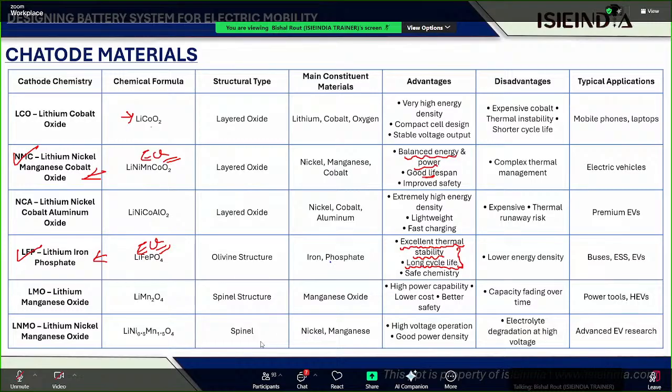So that is the reason why lithium iron phosphate won't work perfectly in cold regions. But NMC will work perfectly in cold regions, and LFP requires preheating beforehand. Let us suppose Tesla is utilizing an LFP cell inside its vehicle, so it is required to preheat it. That is the reason, if you look at Tesla vehicles, they have something called superchargers.